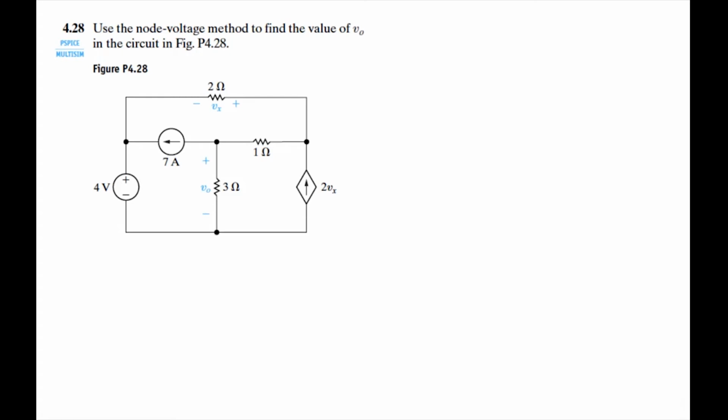Alright, question 3. This is introducing dependent current sources into what we already know about circuit analysis. So what this will mean is that you have to find out pretty much what this voltage is here, so that we know what the current value coming out into this node here is. So we're just going to jump straight into that. We're going to label our nodes first. Let's call this V0. Let's call this V1. And we're not going to forget our reference node, of course.